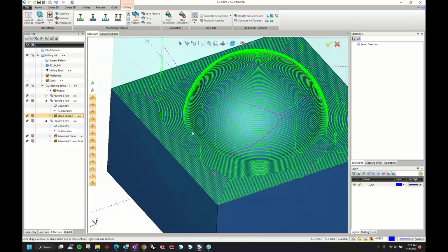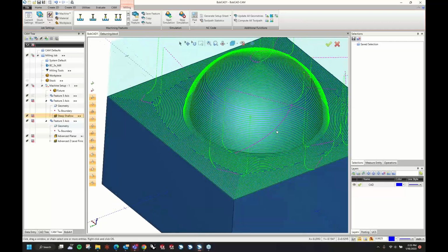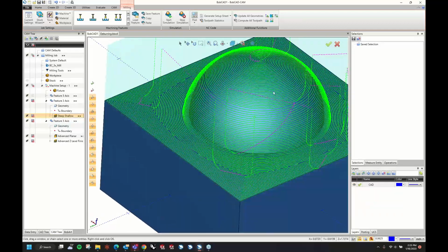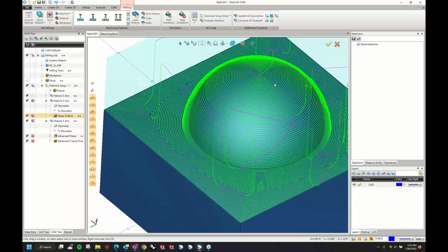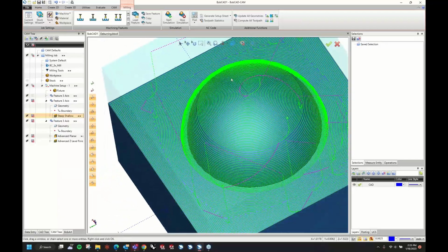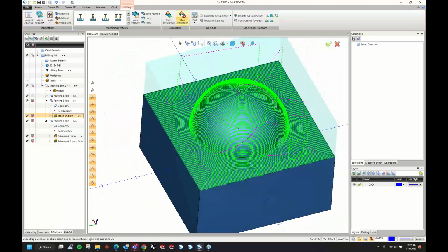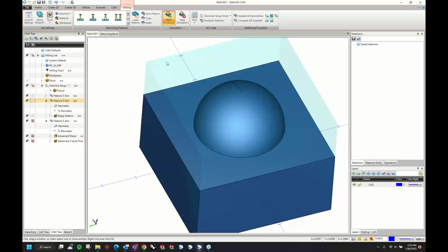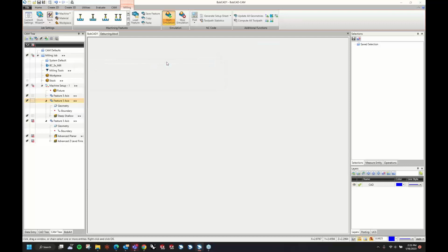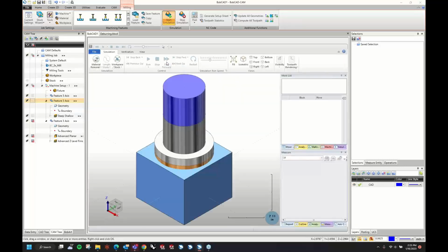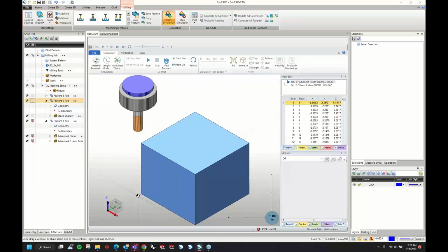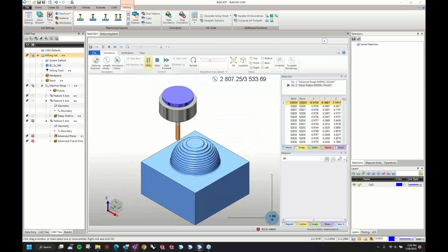So equidistant, you can see it's handling the floor a lot differently. It's an equidistant and Z-level finish. So the equidistant is doing this radial section a little differently than the way planar did. Where you could do the same thing, you just replace the Z-level with equidistant, angle ranges, whole nine. Essentially, this should be very similar, just slightly different cut pattern.